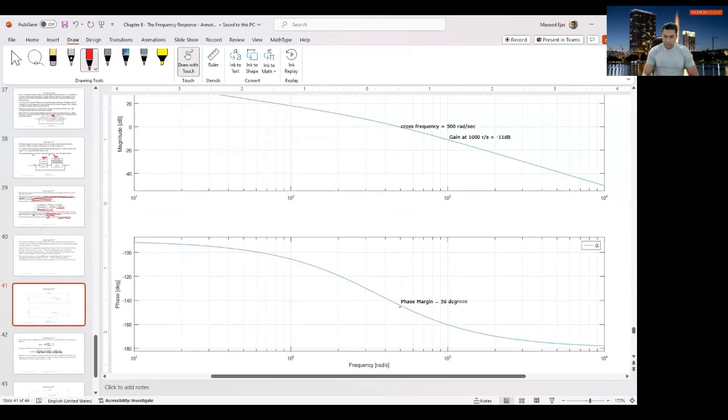And observe what is the phase of your system. So the phase of the system, whatever it was coming out to be, negative 144 or something like that. I did not put the actual value of the phase. But you can see that this is negative 140. And then at 500, it is a little less than negative 140. So approximately it was coming out to be negative 144.